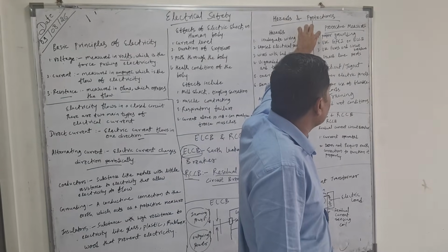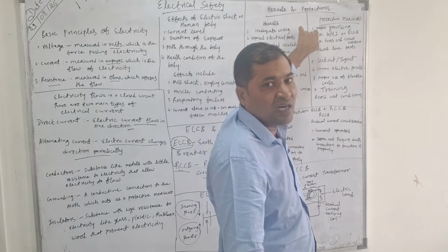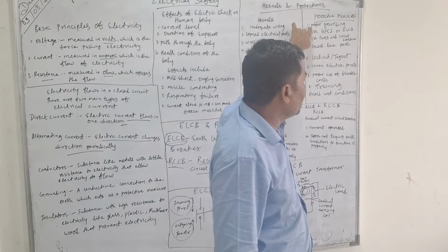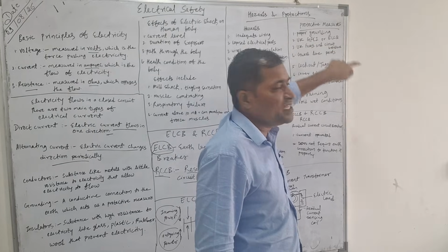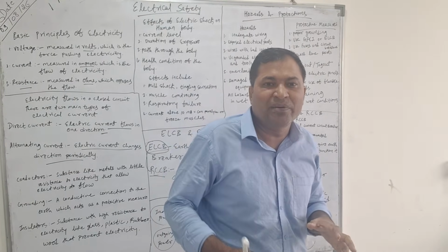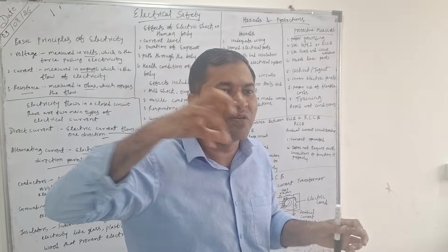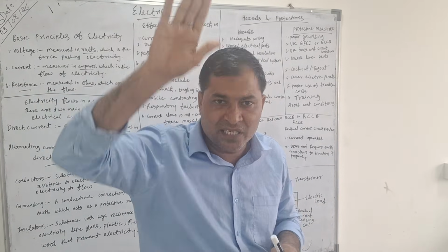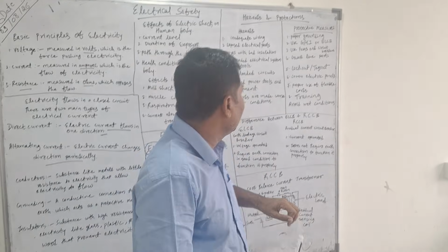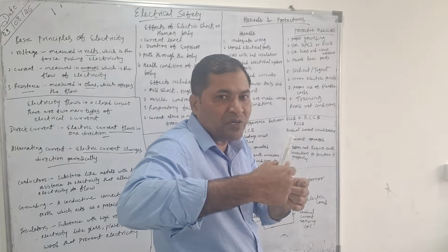For protection, you have to provide proper grounding, make proper connections, and do the earthing system as well. Use a GFCI, ground fault circuit interrupter, or ELCBs, earth leakage circuit breakers, or RCCBs, MCCBs, that kind of system. If you get a shock, the earthing system or MCCB or ELCB will trip immediately. Guard live wires: any live wires, you can guard and protect that part.